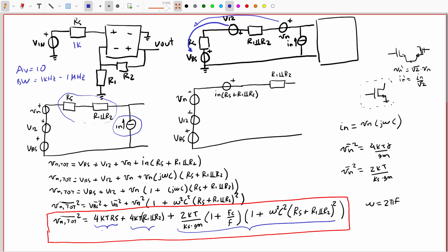There is a number of details that it is important to discuss here, depending on the type of amplifier that we are designing, on the specification that we have for noise. Then we have to make some design choices. In low noise amplifiers, we will want to minimize as much as possible the contribution from the feedback resistors and also the contribution from the input transistors in the amplifier. But we can already see here some implications of reducing the noise.